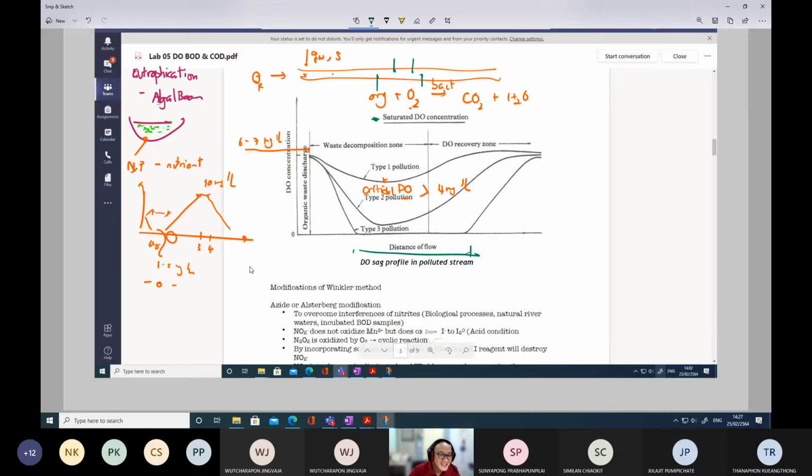Normally, you have to do this every hour, maybe every 2 hours, measuring the dissolved oxygen. After the measurements, you take the information and plot the curve. Some of you have to come in very late at night and also in the early morning to get 24 hours of information. So every 2 hours, you have to measure the dissolved oxygen in the assigned ponds.